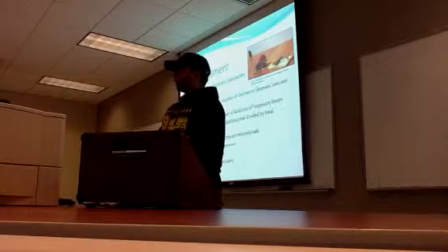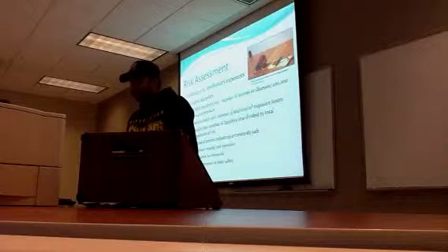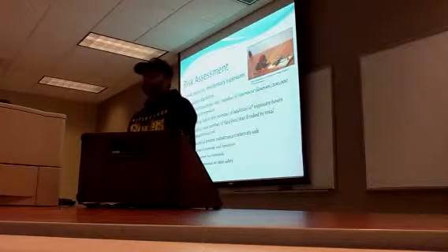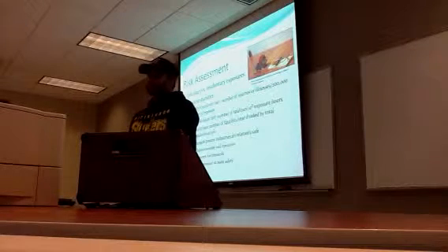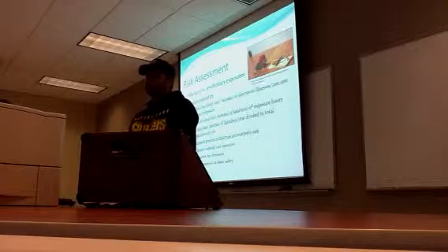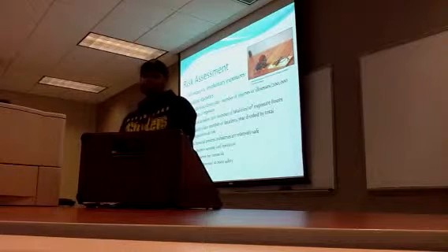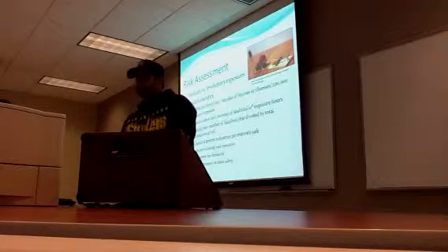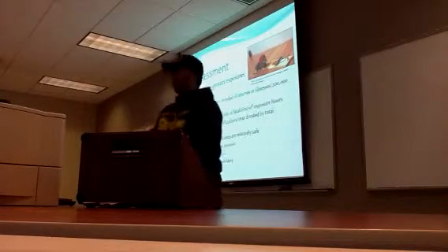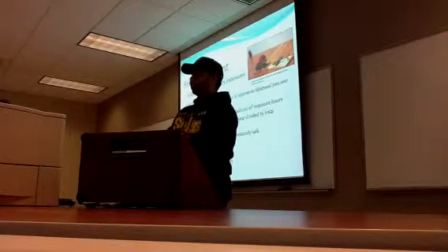And as far as statistics to help you make a decision on risk assessment, there's a few. OSHA has an incidence rate, which is basically the number of injuries or illnesses for every 200,000 hours of exposure. There's also a fatal accident rate, which is the number of fatalities for every 100 million exposed hours. And then there's a fatality rate, which is the number of fatalities per year divided by the total population at risk. And comparatively, chemical process industries are safer because they actually employ a lot of remote sensing and operation.